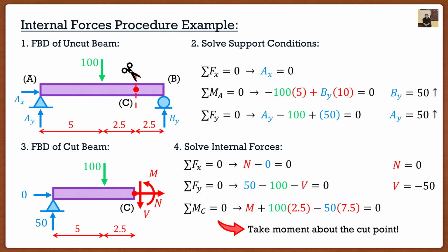Now you guys may be saying, Clayton, why would you do that? Why is this so important? Well, again, it's not going to change anything. If you do moments 100% properly, you'll always get the correct answer no matter where you take it. The reason why I take it about the cut is because that's where my shear force acts. So I don't have to worry about shear force. And you may be saying, Clayton, you just calculated shear force. It's not unknown. You actually have it.